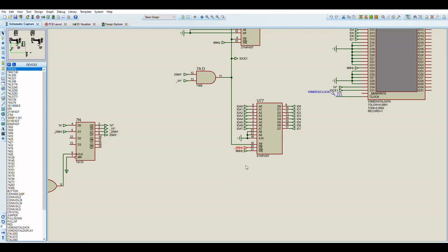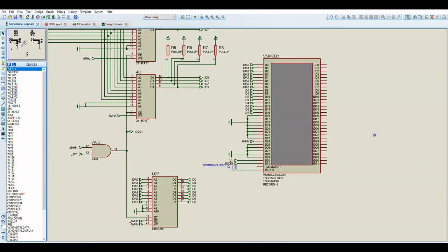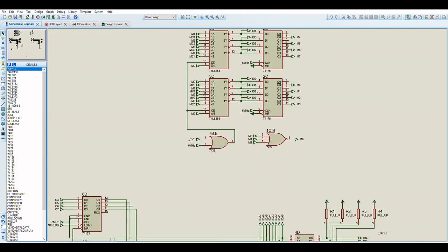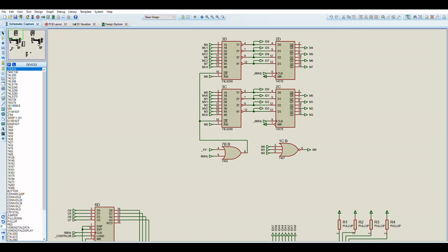For each sprite, the sprite index, color, X and Y positions are read, and that was on the previous sheet. After a successful Y-pos test with the vertical raster position, and with it being within 16 pixels, of course, unless the full screen height sprite flag is enabled, the sprite data counter is set, which is here.